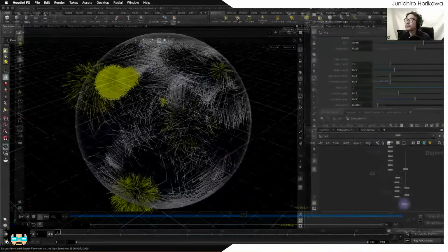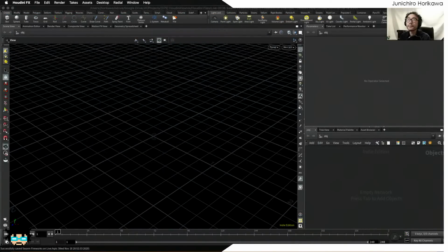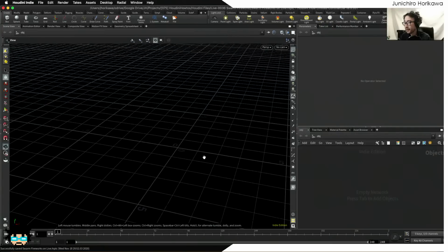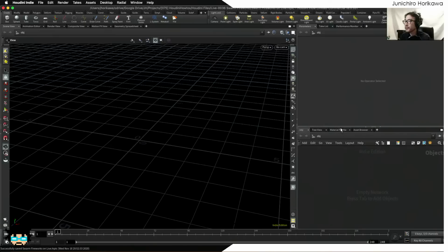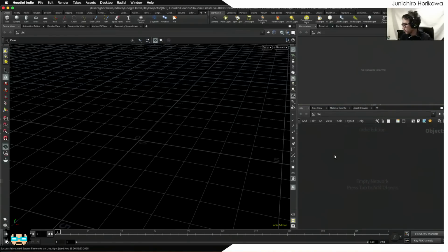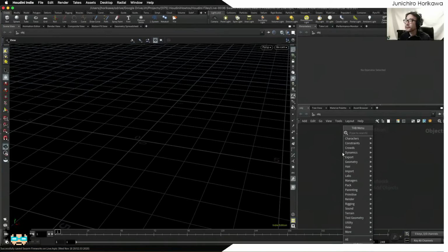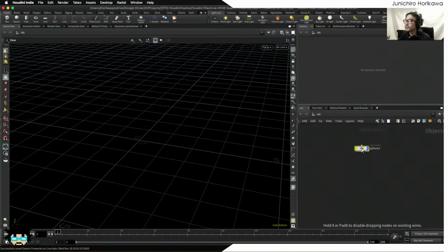Alright, so let's just create it from scratch. First thing we need is to create a basic system for the swarm intelligence, meaning a flock system. So let me do that first. To get started, I'm going to first create a boundary geometry. Could be any kind of geometry. In a lot of cases when people create a flock system, they create a box shape. But since we're dealing with 3D software, let's create some other geometries, starting with a sphere, but it could also be any kind of geometry.